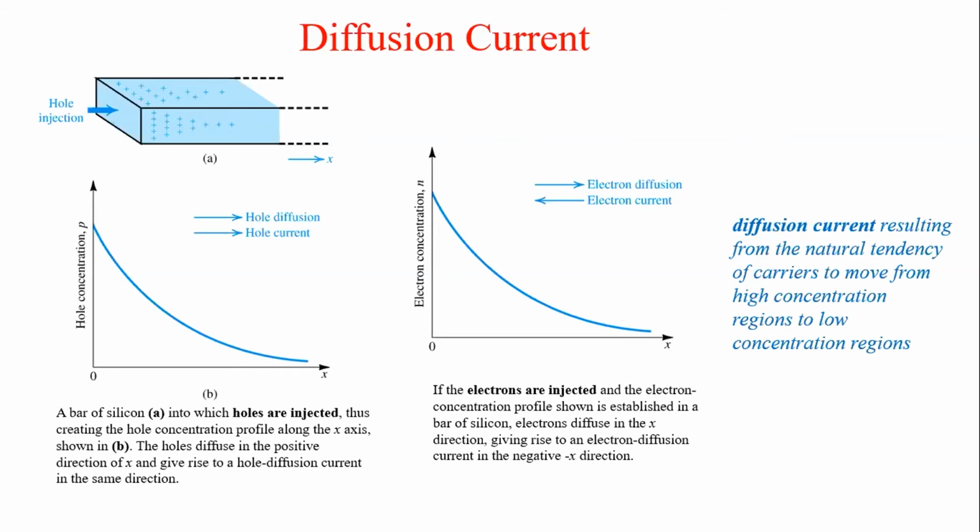So when you take such a wafer and want to dope it, you put it in another process where you can inject, say for example, holes. I will pass energetic boron atoms to hit the wafer, and when I heat it, it starts to diffuse. That way I can dope it. We call that an implantation process.